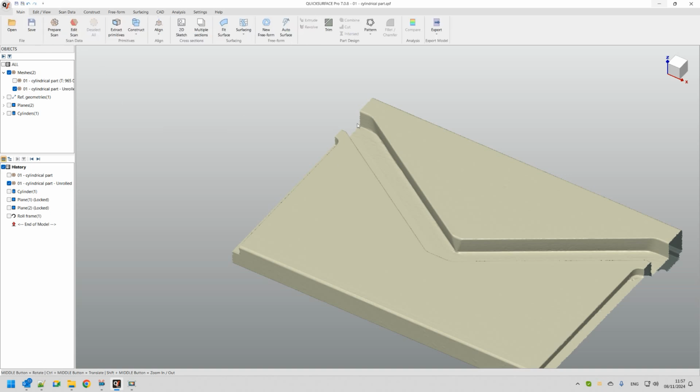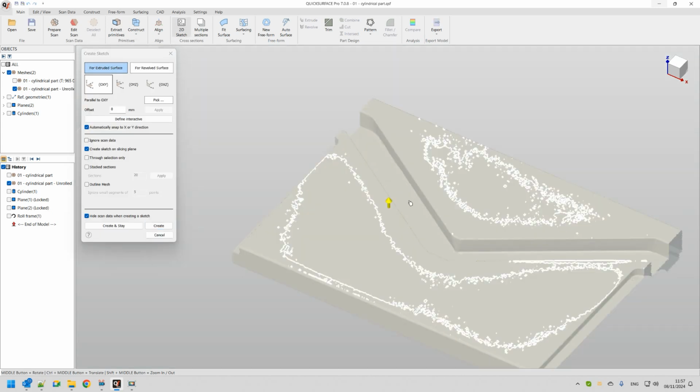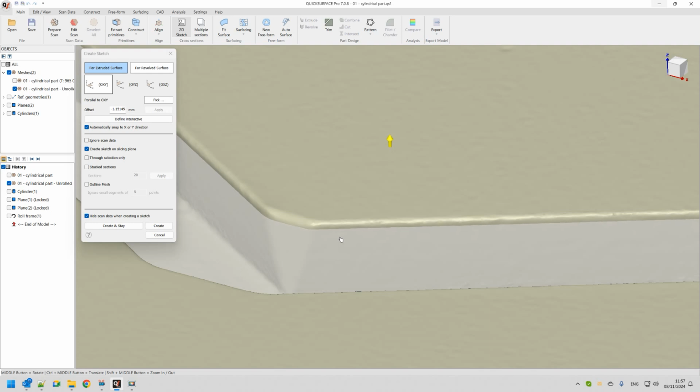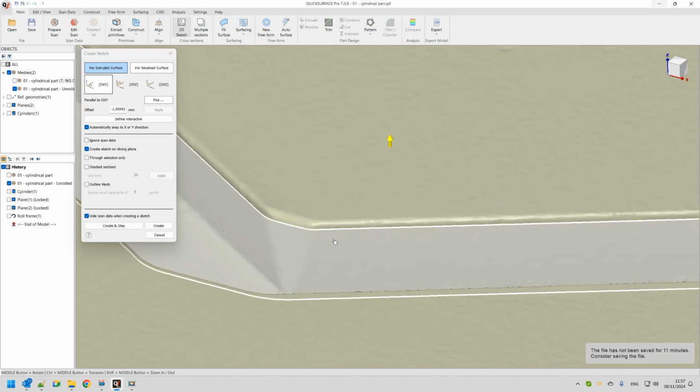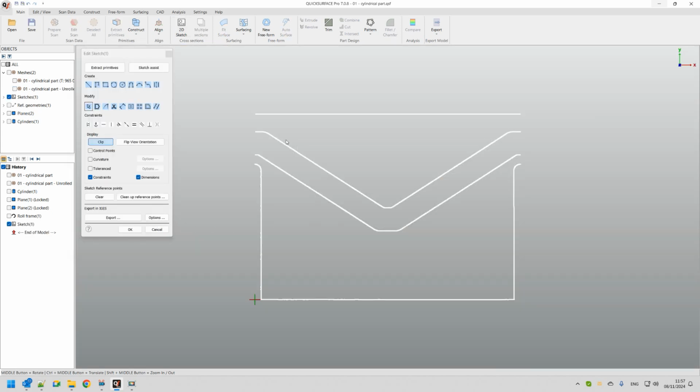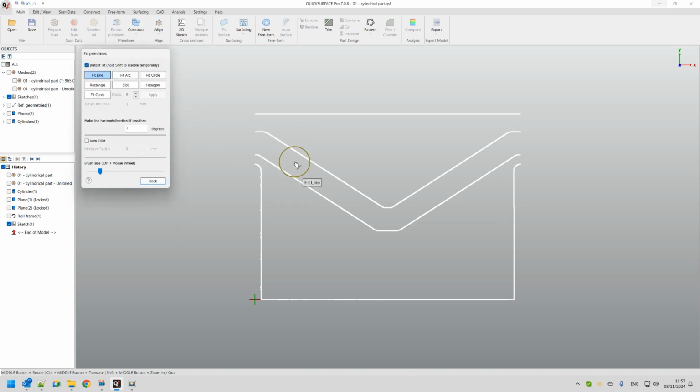What I need to do is reconstruct this shape in a traditional way using a 2D sketch. I'm trying to create a cross section just below the fillet, so I can define a nice and smooth lofting after that, and press create. I'm using the normal methods to extract this profile, just by using the extract primitives.